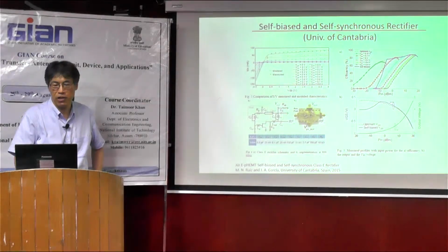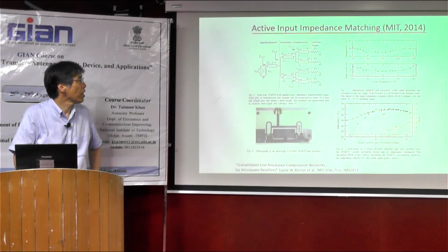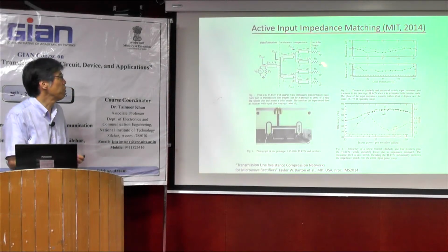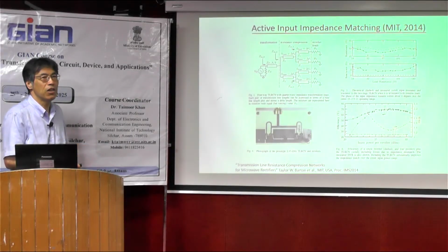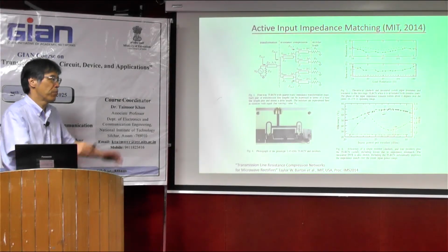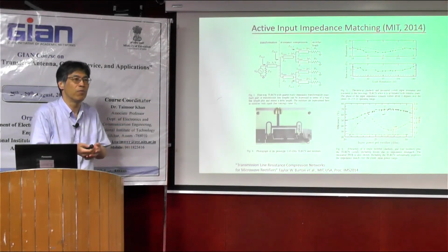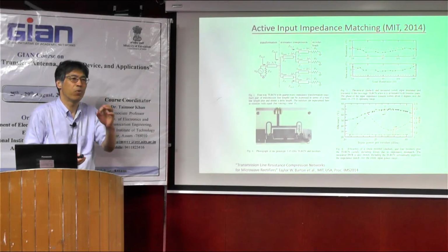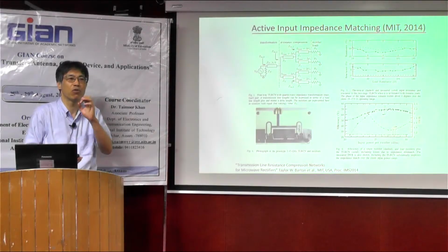So this is a very interesting approach to the microwave detector. And the other group is impedance matching technology, and especially this MIT group proposed an active impedance matching circuit. So in my previous talk, I introduced the Smith chart of the rectifier, and I told you the impedance matching point is only one point in the various frequency, various input power, and various connected load.